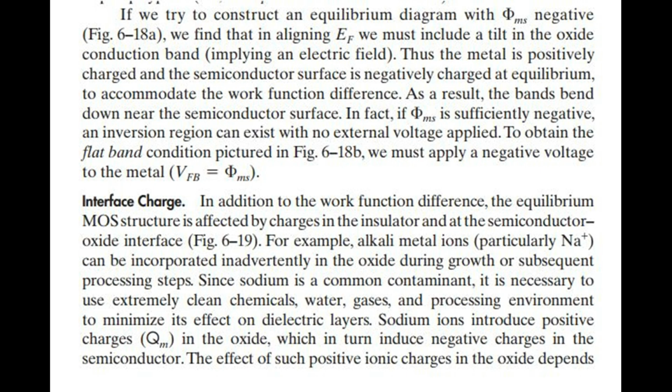Interface charge. In addition to the work function difference, the equilibrium MOS structure is affected by charges in the insulator and at the semiconductor oxide interface, Fig 6.19. For example, alkali metal ions, particularly Na+, can be incorporated inadvertently in the oxide during growth or subsequent processing steps. Since sodium is a common contaminant, it is necessary to use extremely clean chemicals, water, gases, and processing environment to minimize its effect on dielectric layers.